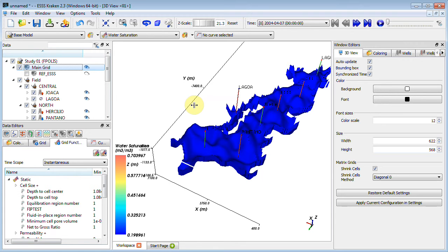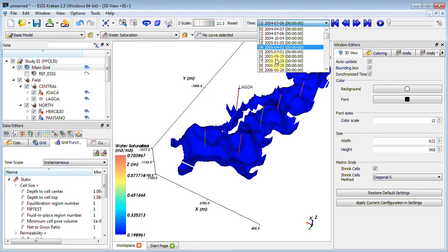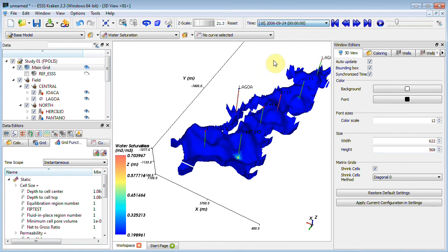There are multiple ways to view later time steps of reservoir life and see the water flooding in this example. A desired time step can be selected from the drop-down menu in the toolbar or via the slider. Additionally, time steps can be stepped through with the toolbar buttons, or lastly, the time steps can be played like a video.